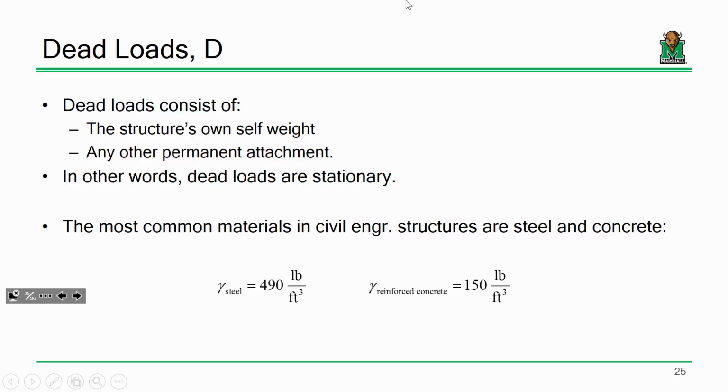We talked a little bit about dead loads. Dead loads are basically the forces that the element is going to be responsible for, comprised of essentially its own self-weight and anything that's permanent, anything that's not going anywhere. So self-weight, the floor slab, some of the main components of the building like the drop ceiling and things like that. Basically anything that's stationary.